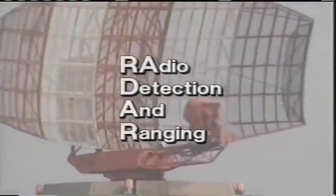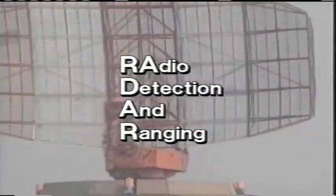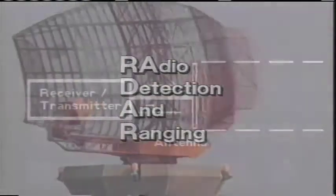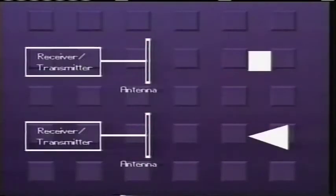The word radar is an acronym for Radio Detection and Ranging, or, in other words, locating targets by means of radio waves. The receiver-transmitter unit of a radar generates pulses of microwave energy which are sent to its antenna. At the antenna, these pulses of energy are focused into a beam. The beam is similar to that of a flashlight's beam. When these pulses of energy strike an object, some of the pulsed energy will be reflected back to the radar.